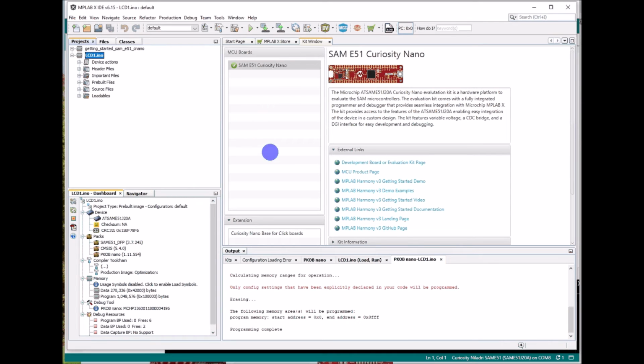So it's a little bit more complicated than just using the straight Arduino IDE, but at least you can use the libraries that you can find for Arduino all over the internet, and you can use the MPLAB to actually load the binary into the Curiosity Nano. So that works for me, and now I just have to get my program running properly.